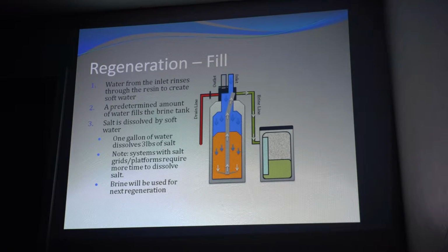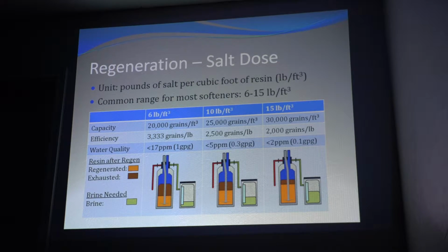So what happens is you're only dissolving, making, 1 inch of brine at a time, okay? And where this runs into a real issue is on high volume twin tank systems. The reason is that a lot of people will put in a twin tank water softener on a commercial application, not only to get that round the clock soft water.